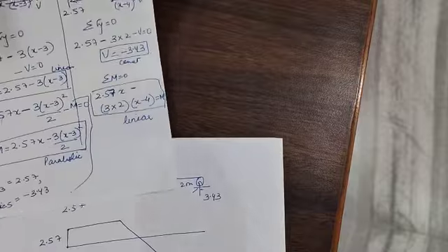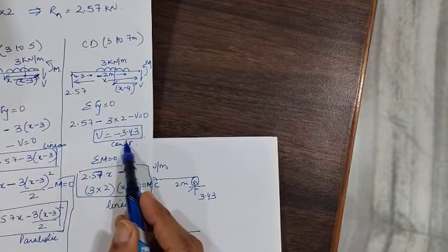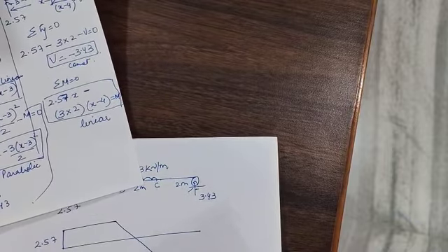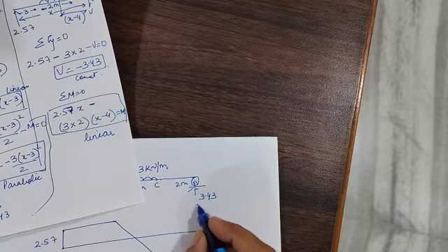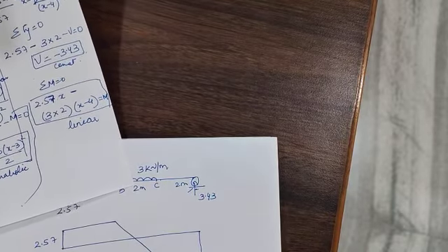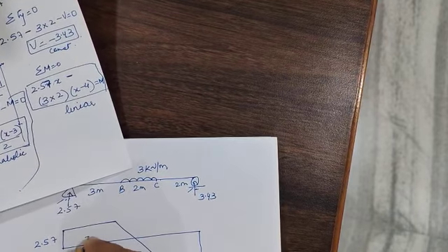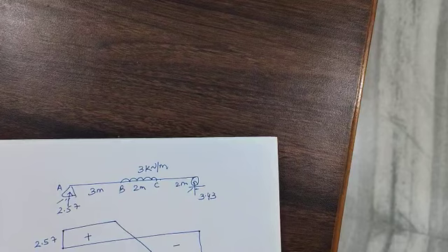After that, your shear force diagram for the next section is minus 3.43 only. So it is constant at 3.43. And at the end, the check is there must be a reaction of 3.43 to bring the diagram back to 0. So your shear force diagram is positive in this section, negative in this section.